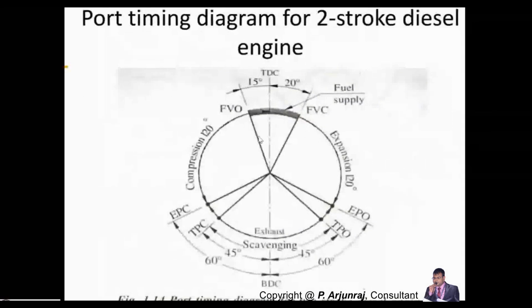First you get the compression stroke. Next stroke is the expansion stroke. And scavenging, where we are going to expel the exhaust, the removal of the burnt gas to the exhaust. And during that time, you're also having the transfer port opening and transfer port closing. So transfer port opening will happen during the charging system, which is nothing but the combustion process. And once the exhaust port opens, the transfer port gets closed. The same process is repeating here.